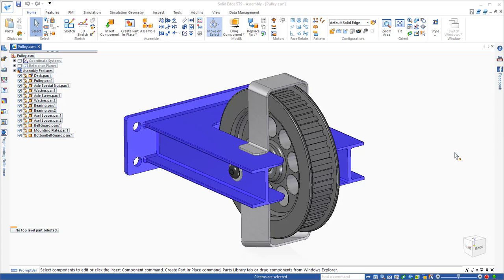And basically this is just one feature on top of another feature on top of another feature to come up with a solid model. If you want to make an edit to that model, you have to roll the model back, find the feature to change, make the modification, and have the model recalculate, which is really prone to failure because you end up with dependencies that you didn't necessarily intend to have.